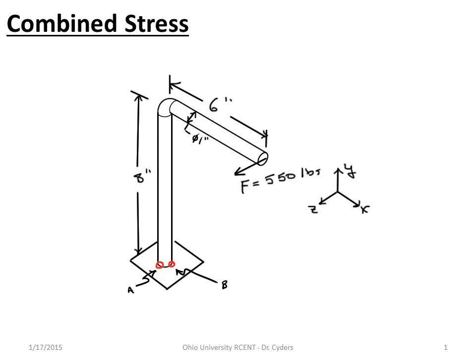The point is, we're going to look down here at the bottom because we have a torsion, or what is a bending moment at the end of this beam around the 8-inch section, which is a torsion. I have a bending moment because of this transverse force, and then I have a transverse shear at the end that's causing a shear stress. And so those three things are going to combine, and so we're going to cut this at the bottom and then take a look at the different stresses.